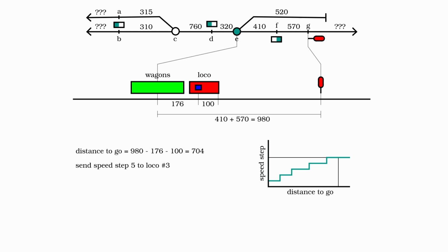We observed from this example that the start of the deceleration depends on the deceleration profile. Different trains can have different profiles. Also, the current speed of the train affects where the deceleration starts, and that is unrelated to where the magnets and block sections are located.